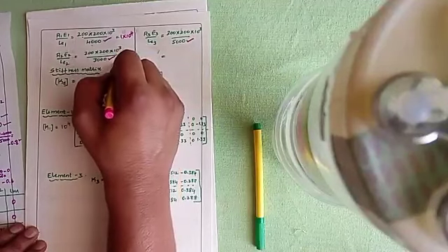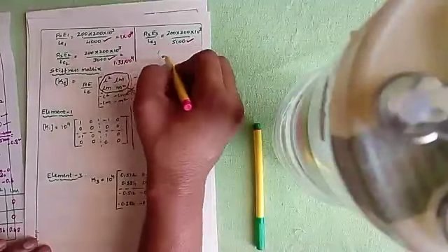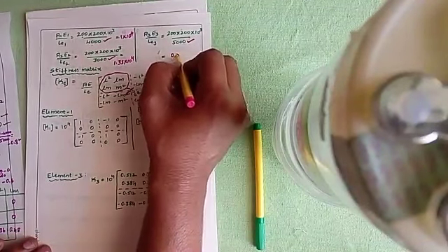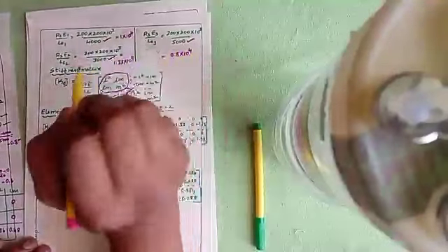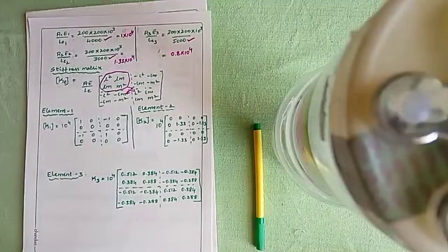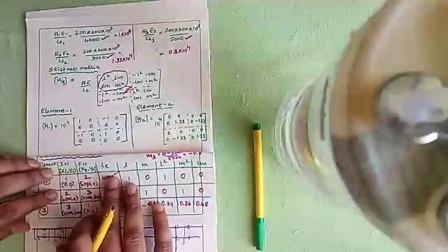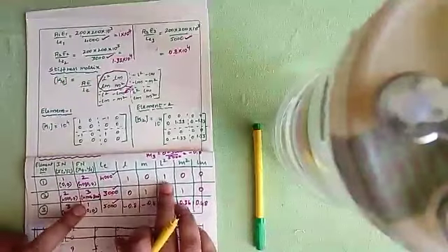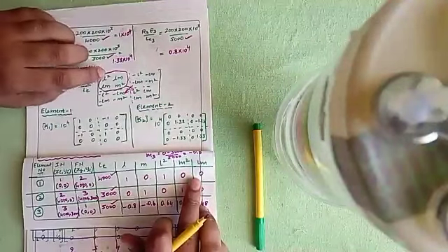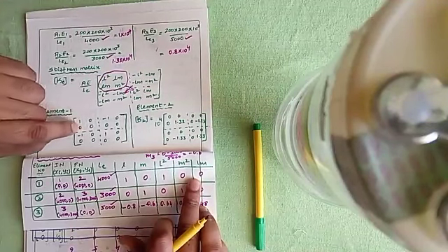Similarly, if you do the simplification for element 2, you're going to get 1.33 × 10⁴. Meanwhile, for element 3, you're going to get 0.8 × 10⁴. Now, by using my element table data, I'm going to form the elemental stiffness matrix for element 1. In element 1, L² is 1, LM is 0, and M² is also 0. So if I write it, it is 1, 0, 0, 0.